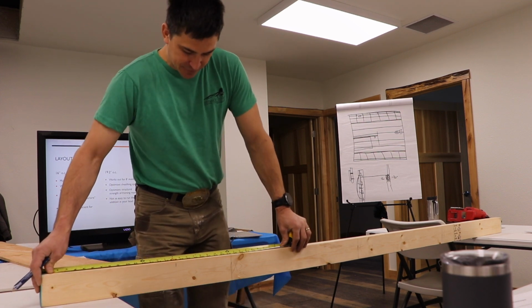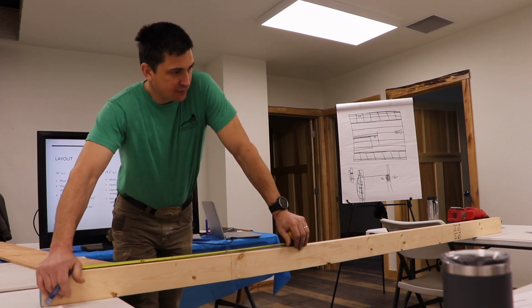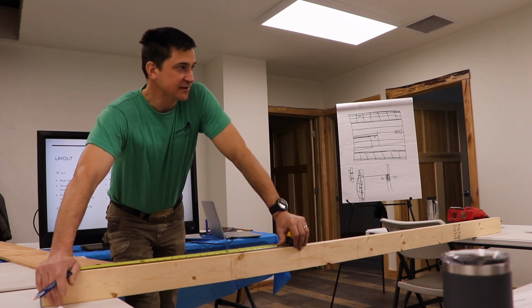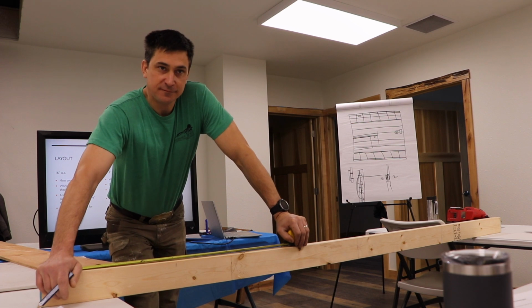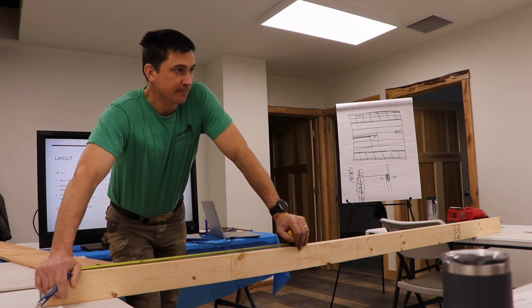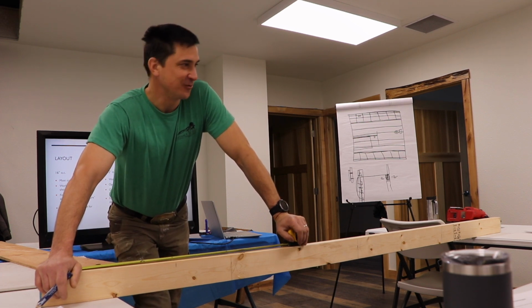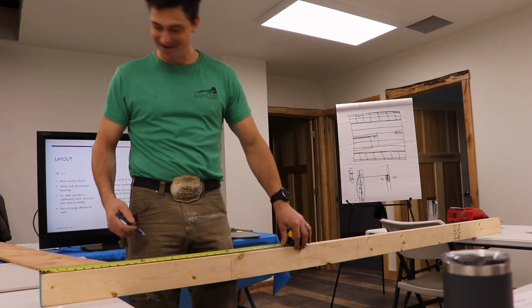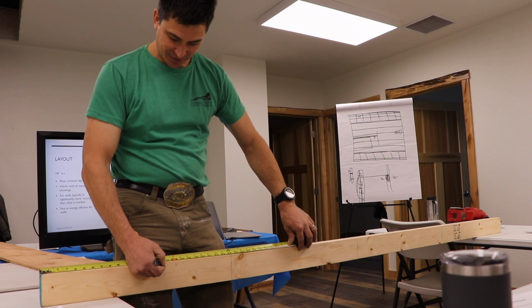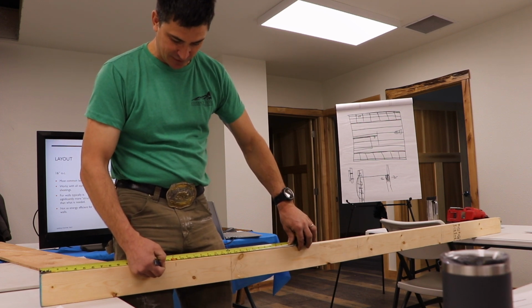So, if I was going to put a 3.5 inch floor truss at 16 inches on center, where would I put my first line? 15 1/4. 14 1/4. Okay, 14 1/4. So Brady can do math better than Gabe today. Okay, so we'd put our mark at 14 1/4.